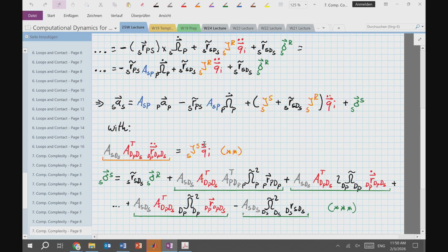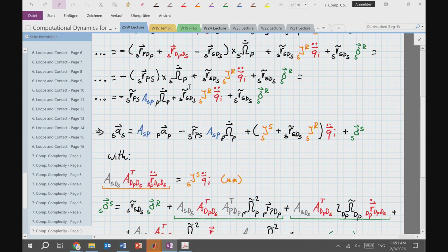Then I have the translational motion of the joint, which is this Jacobian times q double dot. I have the rotational acceleration across the joint, which is this Jacobian times that plus some lever arm. So this shows up here. And all together, you can see how this gives me an overall joint Jacobian. Then this is stuff that depends on the acceleration of the predecessor, right? Linear acceleration is simple. If the predecessor moves with a certain acceleration, the successor should have the same acceleration, just in a different coordinate system. But if the predecessor is undergoing an angular acceleration, then stuff requires some cross products and lever arms that we see here.